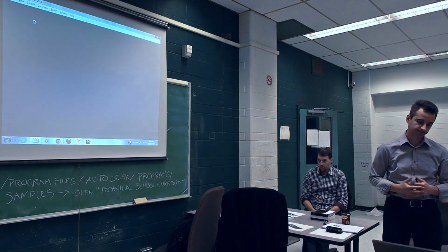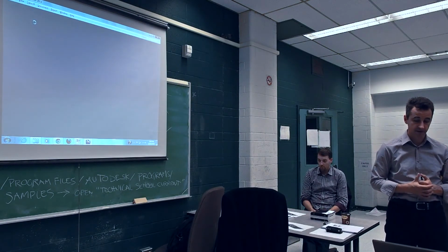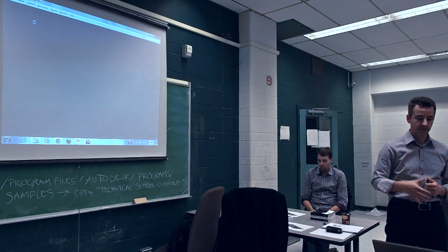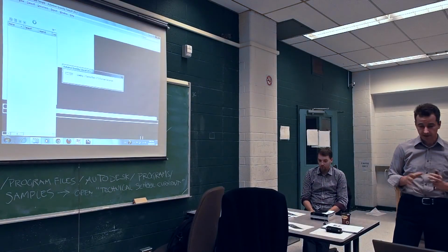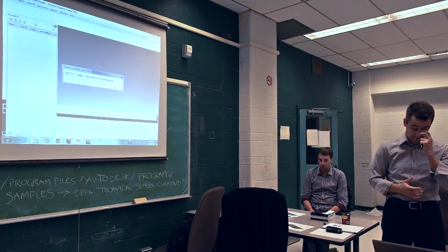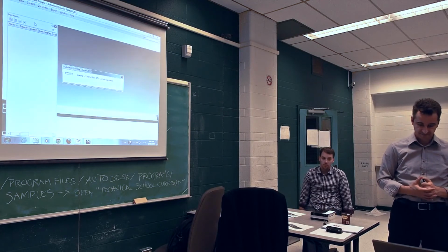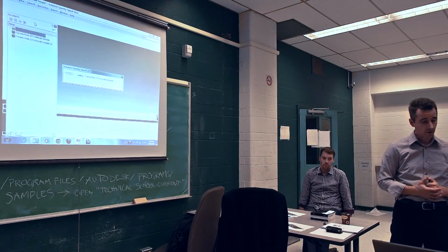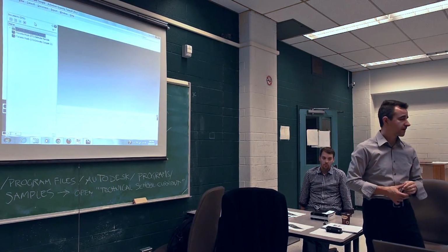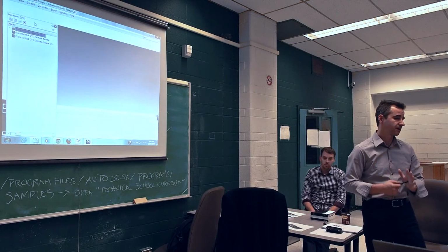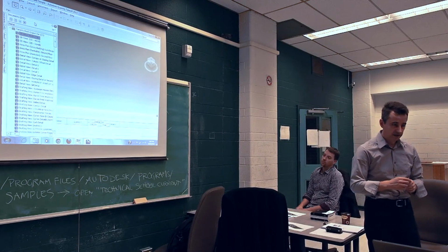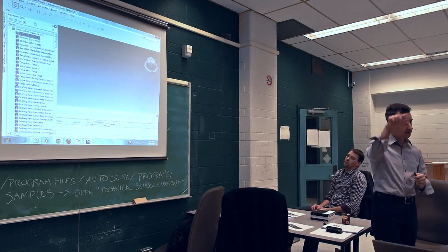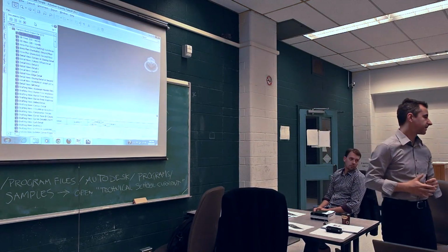It's maybe the most resource-intensive program in this Autodesk building suite. I crashed a few times trying to do this. Okay. So what I did in Revit, I exported my model in DXF. If you go in your application menu, drop down, export, DXF, that's how you export it. Right?